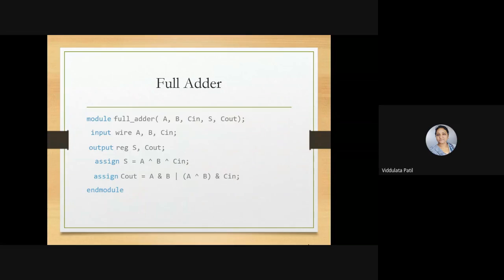So this is the program for the full adder. The module name is full adder, that is the name that I have given. Then the port list: A, B, C in, S and C out.